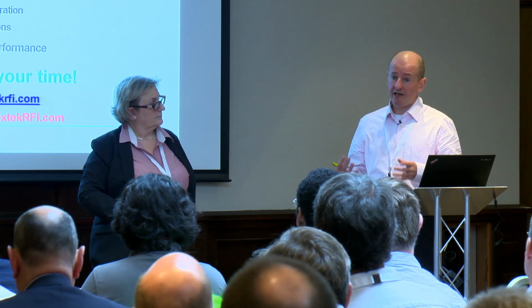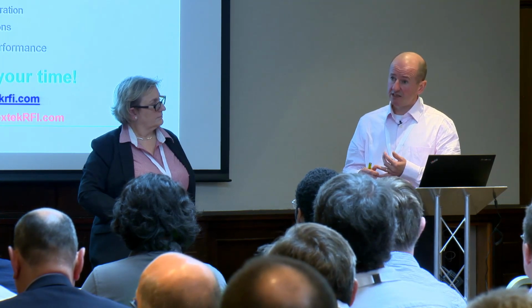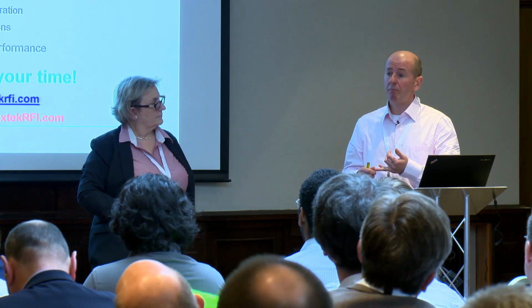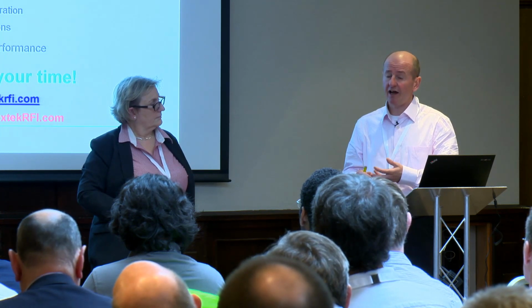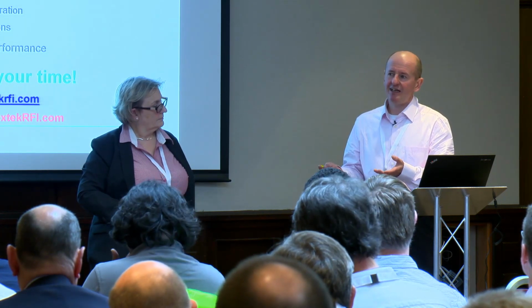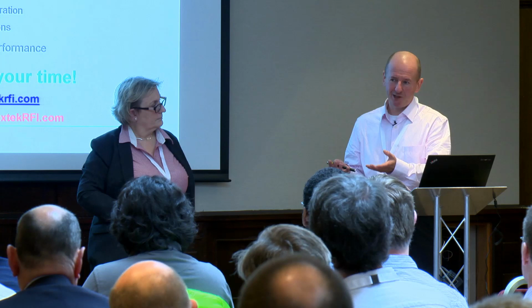But people like MACOM, for example, they have both GaN on silicon and GaN on silicon carbide. And your performance does suffer. You get less output power per millimeter of gate width with silicon. It just isn't as good thermally. However, it will be cheaper. So you have to weigh up your performance compared to your cost. And each different application results in a different choice. If you can get MACOM to tell you which they've used for which, that'll give you some good insight into where the choice cuts off.